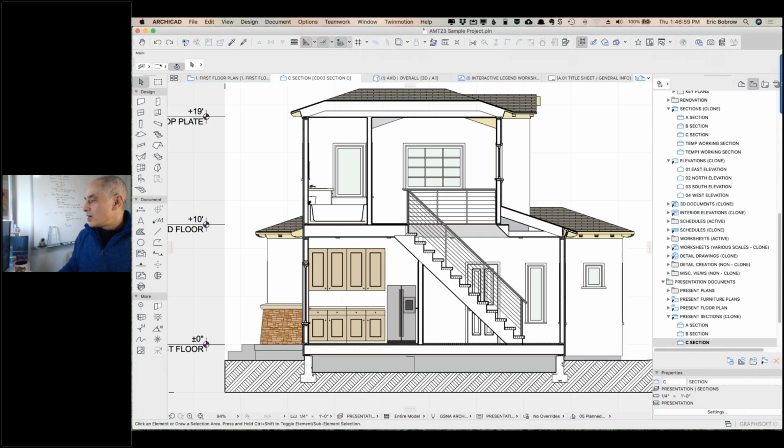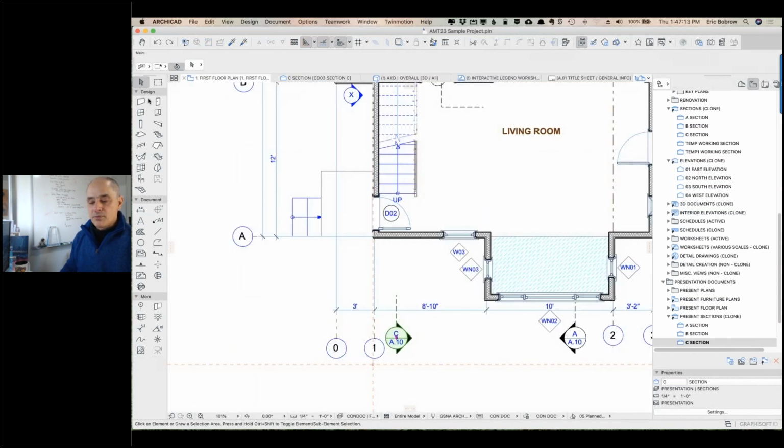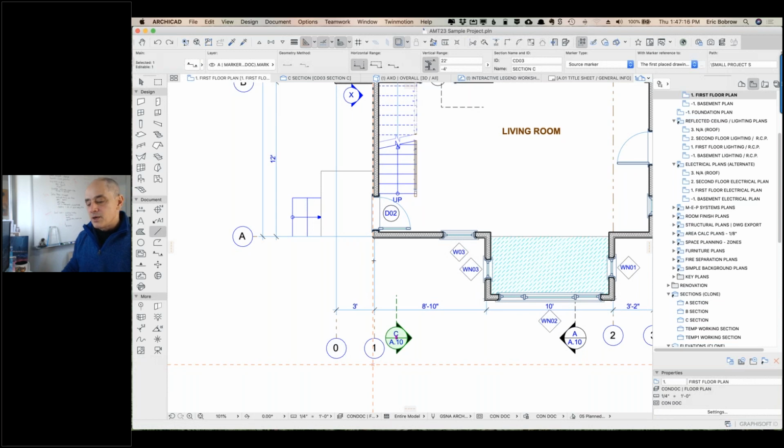All right, so Tom says, type Q to have the blue guidelines or circles show up instantly. They appear after the prescribed time in the profile manager otherwise. Okay, so that's a good little tip here. So if I'm drawing, I'll just go to the line tool here, and if I hover over this wall, after about 2 or 3 seconds, we got that little blue highlight. If I go to the corner, after a second and a half, it brings up that snap point, and now actually I have the ability to snap in relationship to that.